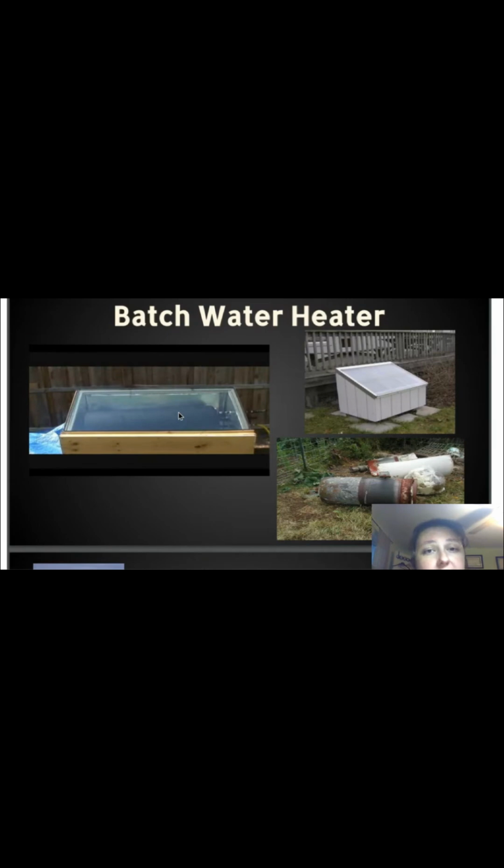Now, this system is located in the local Stamford area, so Stamford, Connecticut, and we use it for part of the year, but once we start to get to temperatures below freezing, we just close down the tank. We actually drain it, because we're not going to try to use any type of fluid system. It's an open system that allows us to take advantage of the heat energy. And so we drain it so that it doesn't crack in the winter, and then we use it in the spring, summer, and fall.